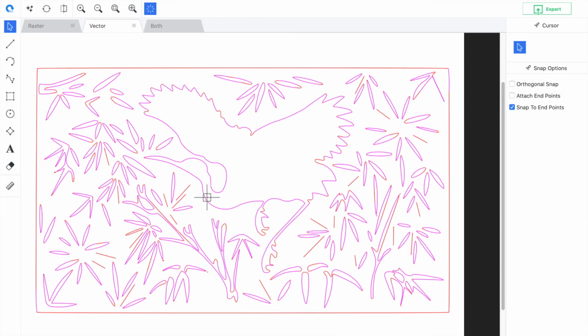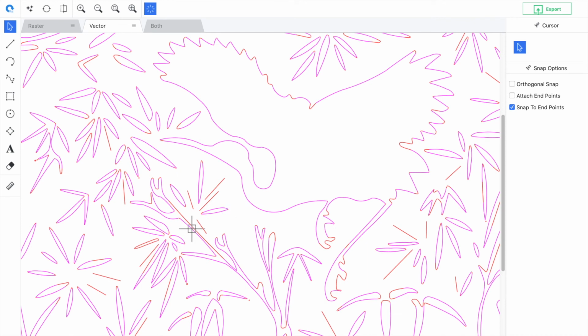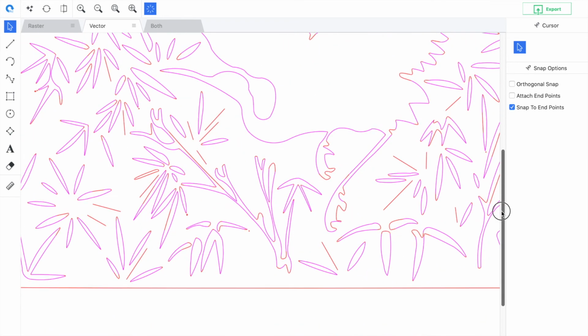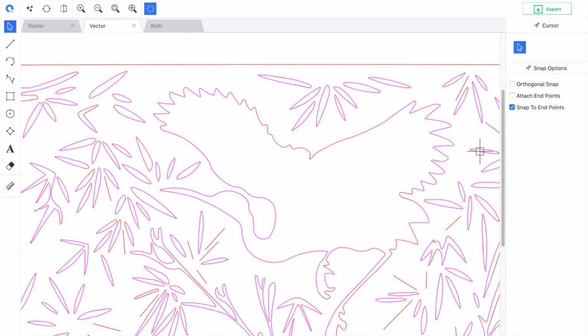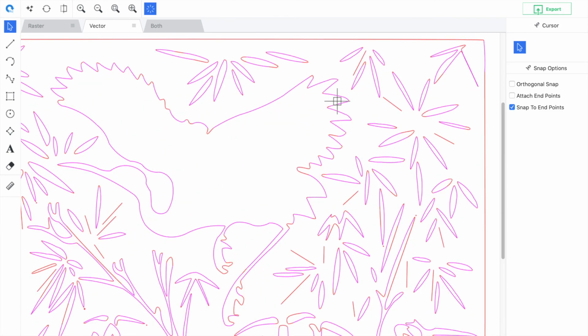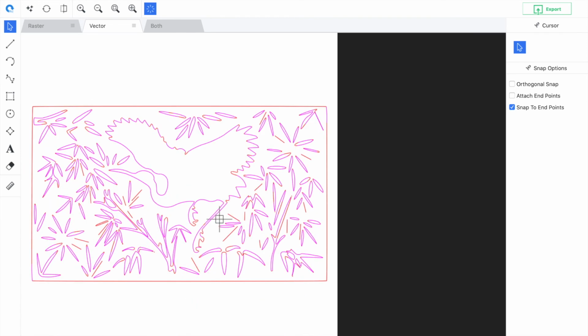We'll hit the highlight button again. So again, ScanCAD has, where possible, reduced the vector elements to as few as possible whilst representing the original vector image. So we can see the head of this bird now is just one arc. And again, that's as few arcs as possible whilst following the original profile of the image. So this is a really good example of how we've significantly reduced the number of vectors and made this image suitable for CNC cutting. The final step is just to save out the file now.